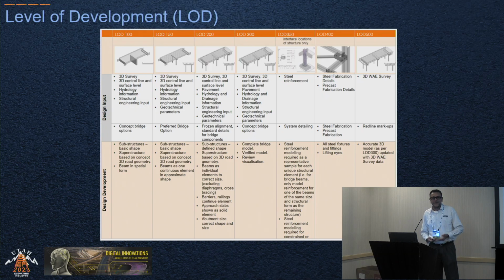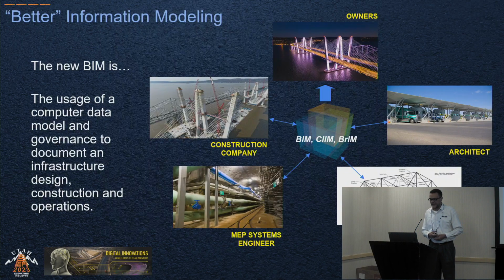data. So in the design world, we typically stop at LOD 300, which is accurate information. Hand it over to the construction side, fabrication, that's where you start to get to these higher levels of development. But now we're starting to see, for design of bridges, we're going to LOD 350 and 400, because now we have the capabilities to do that. So we're showing all of the rebar. We're showing all of the bolts in a steel bridge. They're all defined, they're all geospatially oriented, they all can be referenced, but they're very precise and exact.